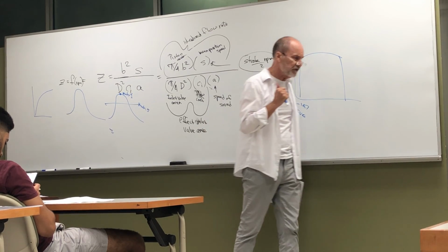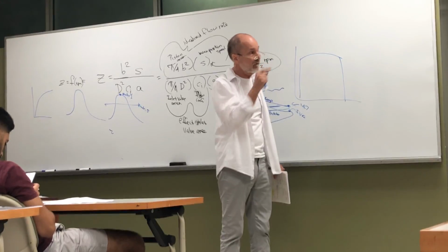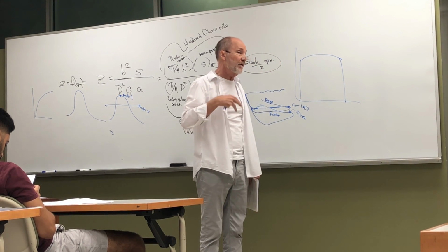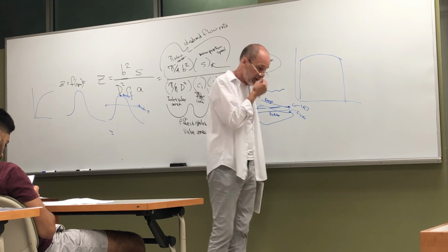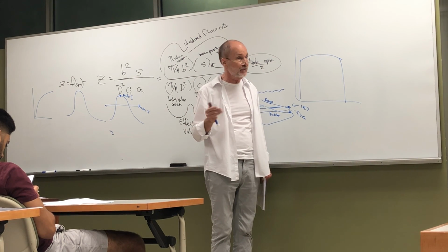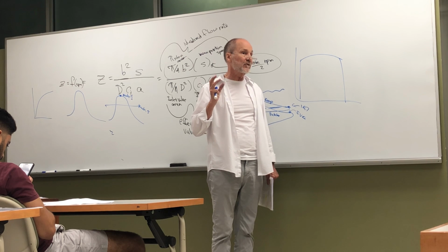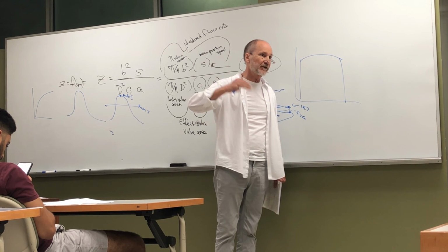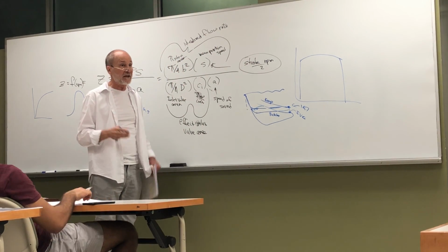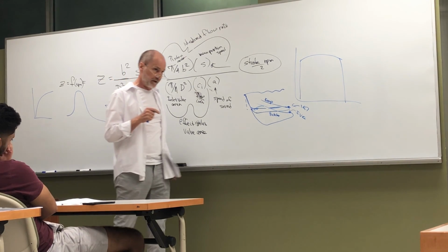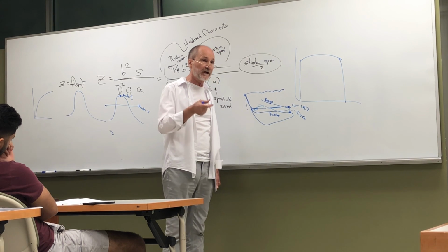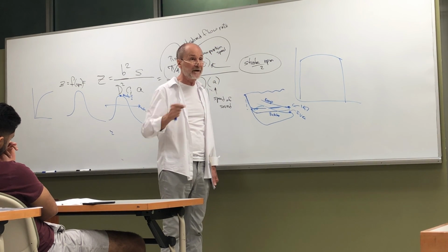We'll see in future discussions that sonic throttling intake valves, which is what we're employing on the engine downstairs that reaches 38.8% thermal efficiency, produce a wonderful result in terms of burn rates. You can burn a very lean mixture very, very fast, and yet we don't have the bulk gas motion that causes the big heat losses in the combustion chamber. BMW was the first company to do it. They developed sonic throttling intake valves. When you're driving a post-2001 BMW, you can actually open and close the throttle when you're starting it. The rest of the time, the throttle's wide open and they're varying the lift.